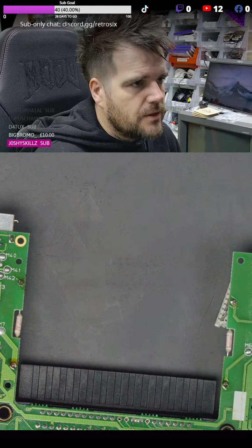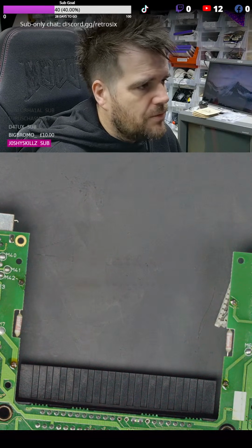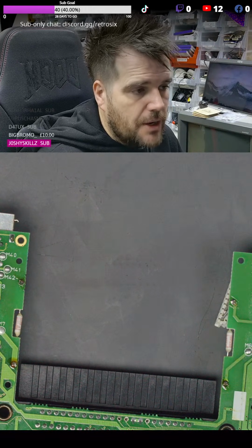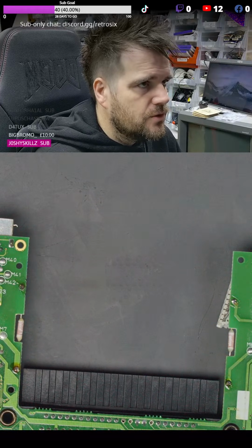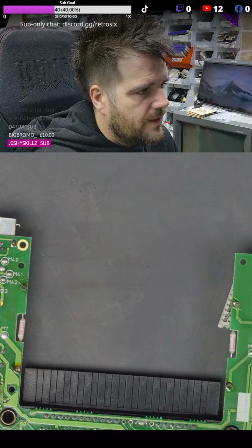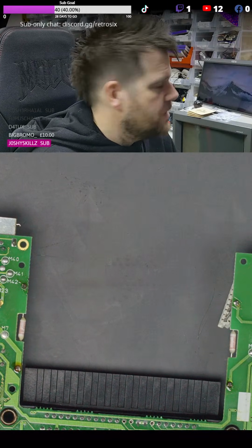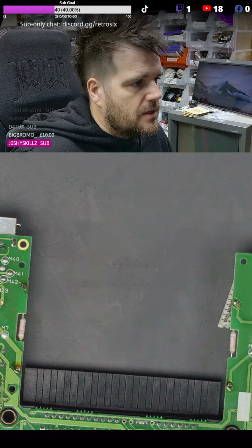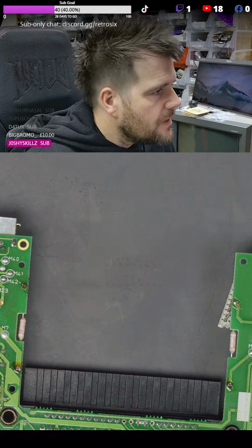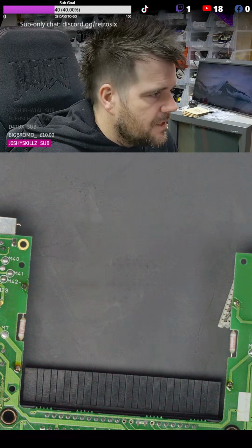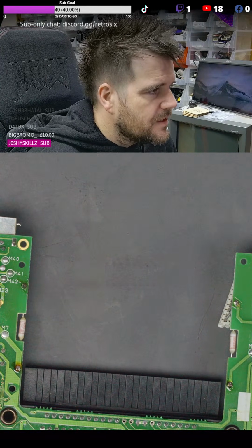I'm going to do a short on this board that acts like probably one of almost the most common shorts, which is when a component actually fails and it's not a dead short. So let me just start by effectively making a short on this board. I just need to check something a minute on the schematic, and then we'll get going. I should know this off the top of my head by now. I've worked on the Game Gears that much, but I still forget the pin out sometimes of things.